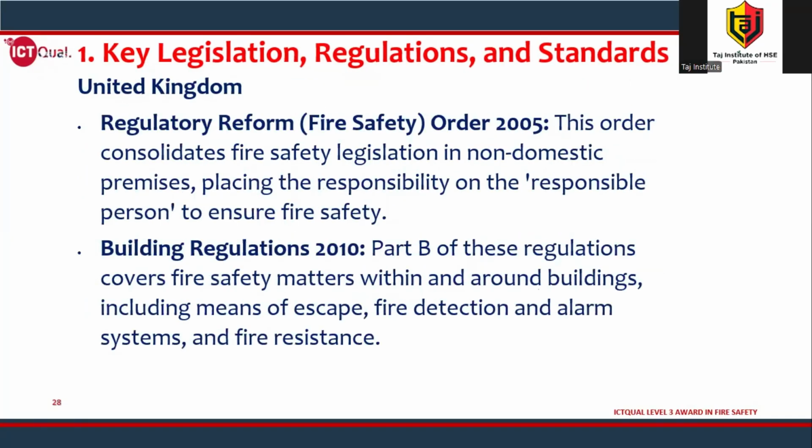United Kingdom: Regulatory Reform Fire Safety Order 2005. This order consolidates fire safety legislation in non-domestic premises, placing the responsibility on the responsible person to ensure fire safety. Okay, and Building Regulations 2010. Part B of these regulations covers fire safety matters within and around buildings, including means of escape, fire detection and alarm systems, and fire resistance.